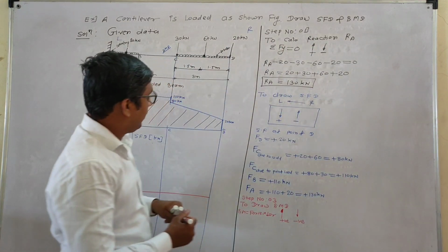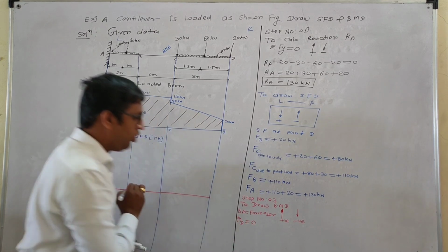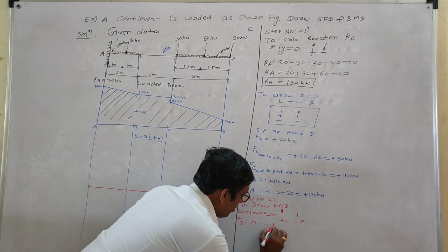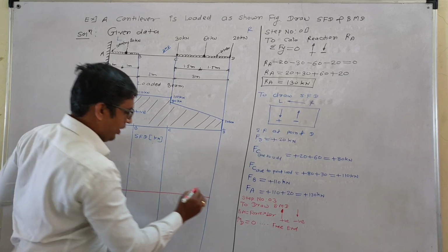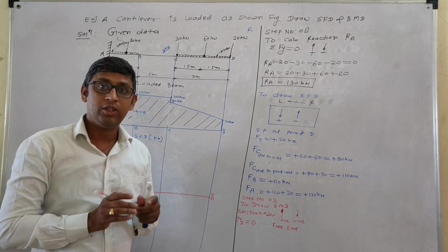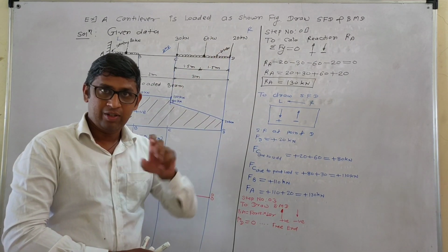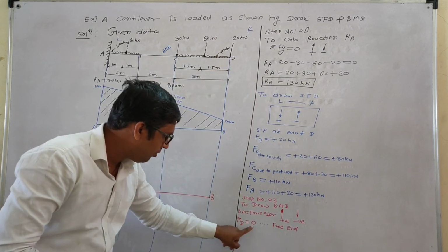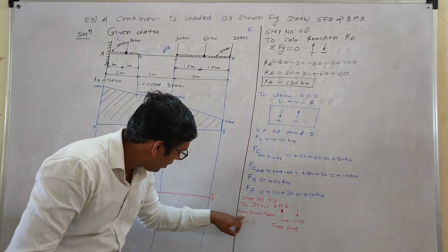Okay. Then bending moment about the point D is equal to 0. Why 0? Because it is a free end. At the point D, bending moment is 0. So many students are writing bending moment at point D is equal to 20. Some students are making the same mistake. Bending moment at D is equal to 20. But our concept is what?